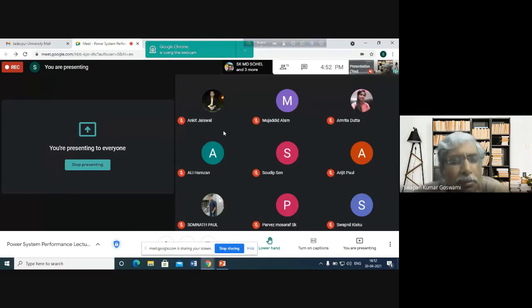How many conductors may be there in a single stranded conductor? Maybe 6 plus 1, that means 7 conductors, maybe 12 plus 6 plus 1, that means 19 conductors, like that. Inside there will be one conductor, surrounding that there will be 6 more conductors, surrounding that there will be 12 more conductors. In this way, conductors are arranged, and all these conductors are electrically touching each other, spiraled together.